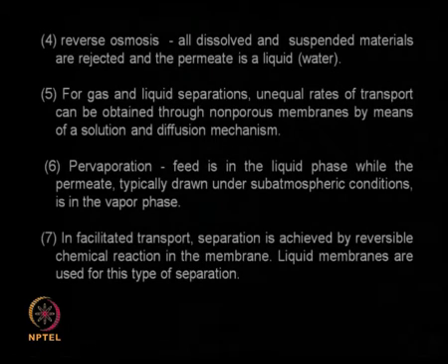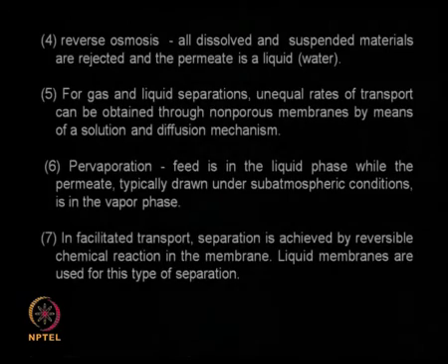So there are many different types of membrane techniques available, and each technique operates on a different principle. It could be a concentration gradient, a pressure gradient, osmotic pressure, ionic forces, an applied electromotive force, or the rate at which certain material diffuses through. For all these reasons you can get a separation.